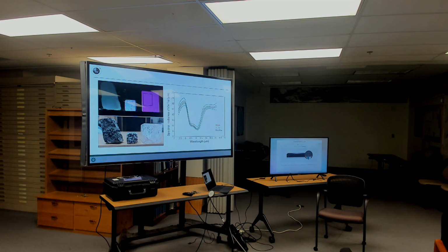Right? We were seeing changes in absorption in the visible part of the spectrum, which is why they look different colors, but all of the paper was kind of reflective in the infrared. Similar thing here, the emissivity at wavelengths that our eyes can't see is the same for those different colors, which is why the brightness temperature doesn't change when I rotate from black to white. But the bare aluminum, and also these scuffs, and that's a bit of rust at the top there, are giving me very, very different brightness temperatures.